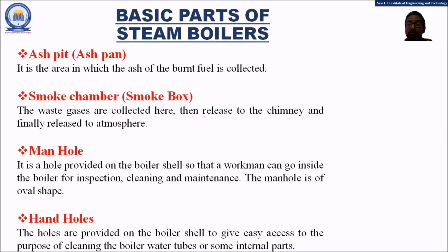Through the hand holes only the hands of the boiler operator will enter, and by entering the hands, the operator can clean some internal parts as well as the boiler water tubes. And friends, cleaning through the hand holes is very important to have maximum heat transfer.